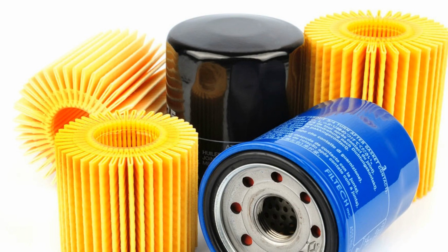Working of the power unit dry is fraught with rapid heating of the rubbing surfaces to a critical level, after which, due to thermal expansion, there is a decrease in clearances with subsequent destruction of engine parts subject to increased friction. The complexity of the realization of the engine lubrication system is not only to ensure the delivery of lubricating fluid to the right place, although this is also a difficult engineering task, but also to ensure the circulation of machine oil in a closed cycle with minimal losses.